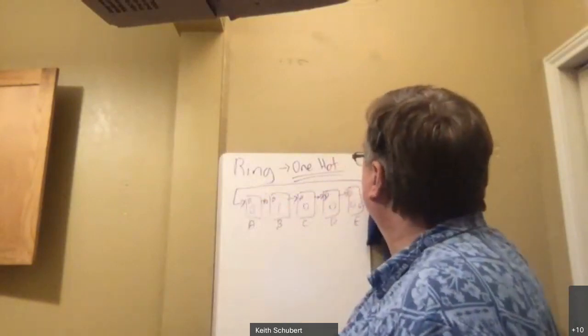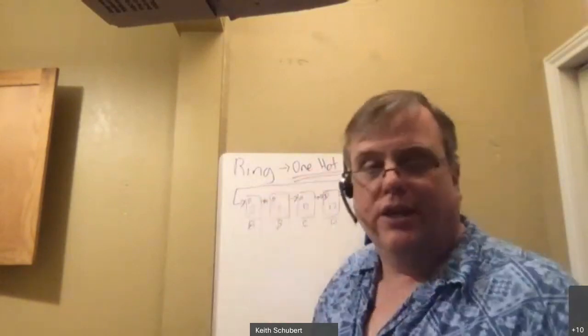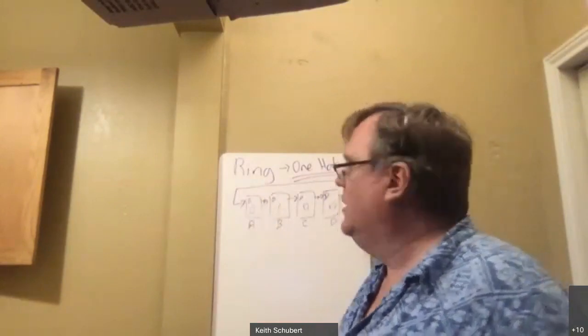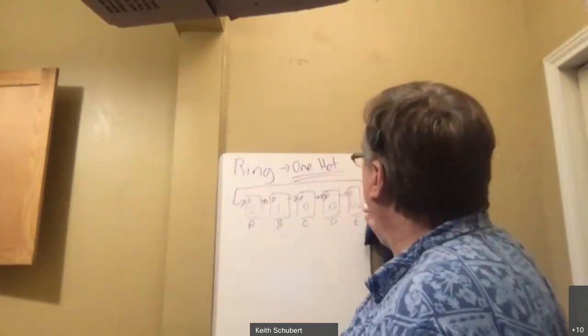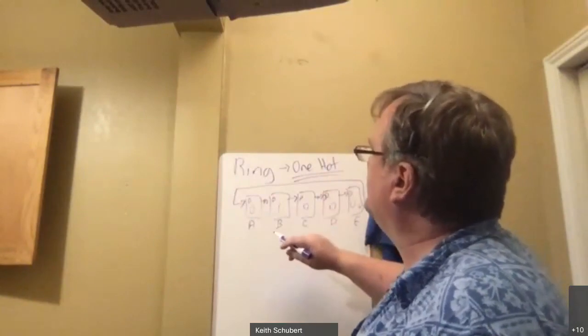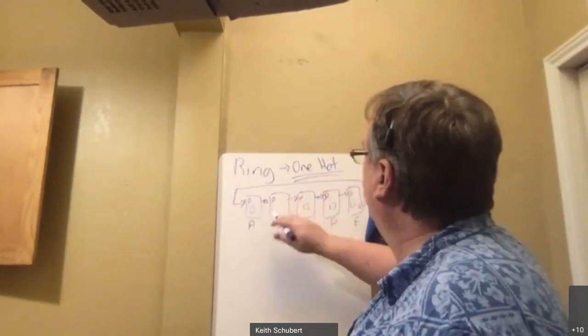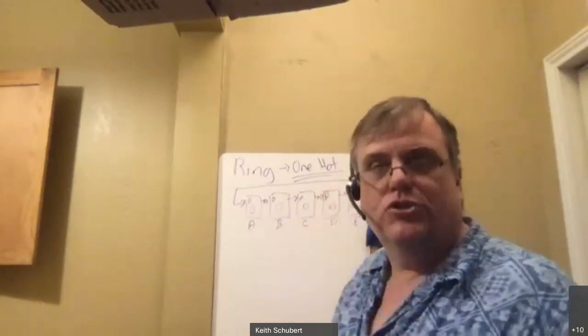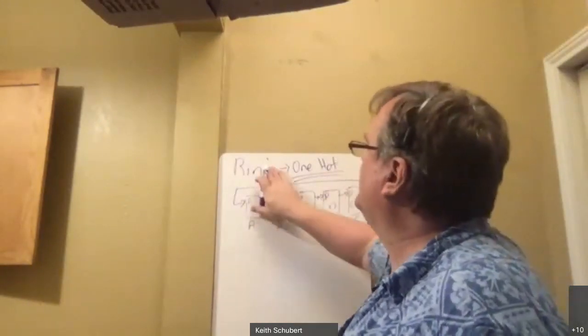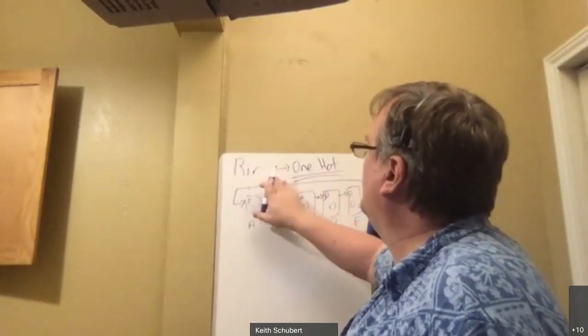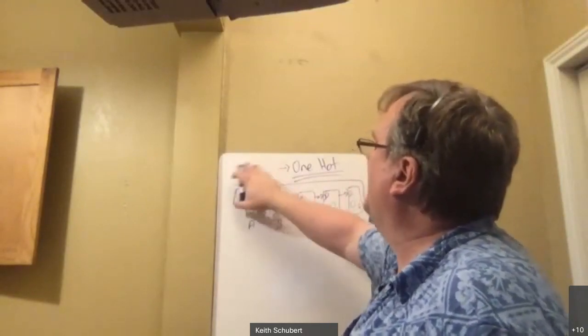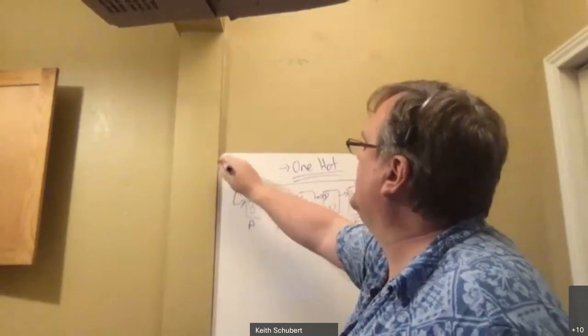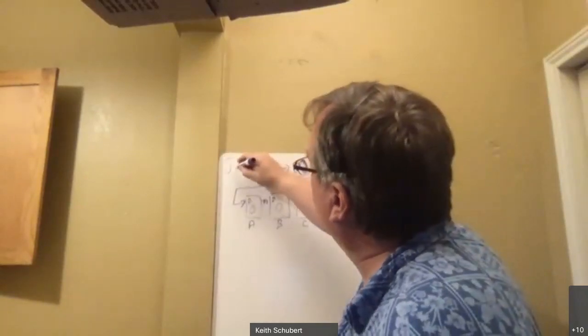You can also think of it as taking it from Q and putting in an inverter in the line. Now, if I do that, it's basically a ring counter, but there's this inversion in the system. Now, we'll start at all zeros because I'll generate 1s from this inverse that's coming in. This ring is no longer called a ring counter. It goes back to the last name of the person who invented it, a Johnson counter.